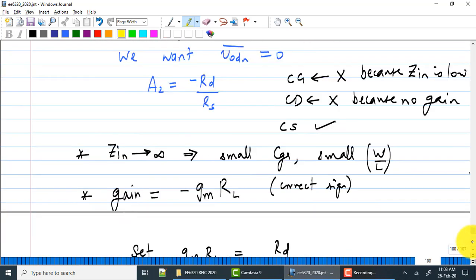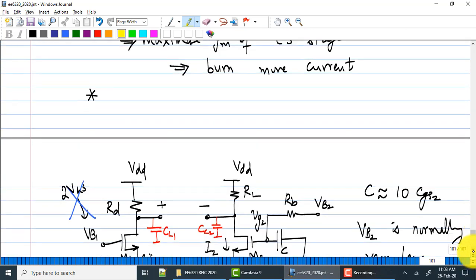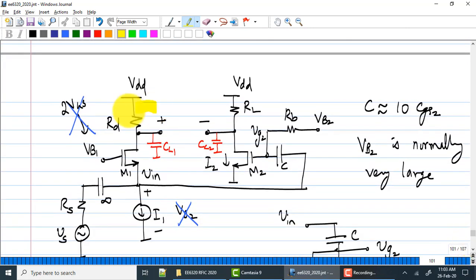So the noise cancelling LNA consists of two portions, okay? A common gate portion, which is here, and the common source portion, which is here. The common gate portion helps you achieve input matching to 50 ohms through its 1/GM input impedance, okay? But it's noisy. The common source stage helps you cancel its noise at the output, okay? Obviously, you need to ensure that the noise of the common source stage itself is very low compared to the common gate stage, okay?